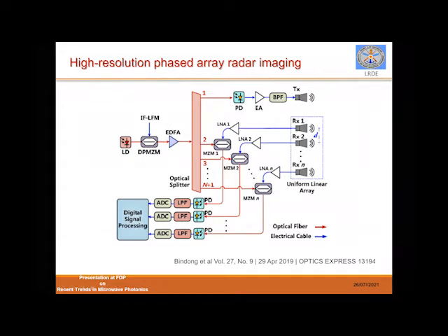There are various types of methods for RF signal generation. So they are talking about frequency quadrupling, where if I give an LFM waveform, I'm just telling you one example only, assume that I'm giving 250 megahertz or 125 megahertz center frequency, and the bandwidth of each signal is 50, say. So the output of this quadrupling will actually be 4 times the center frequency as well as 4 times the bandwidth.